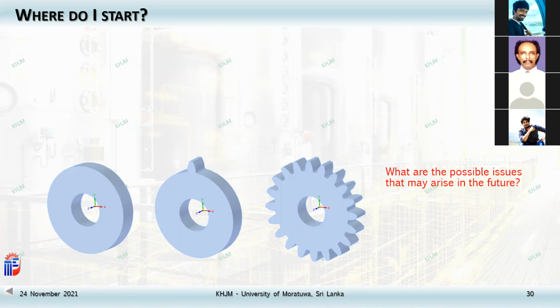You know the motor speed, you know the output speed, the required speed. So you divide, then you can get some values. But based on that, then you calculate the number of gear teeth. The number of gear teeth cannot be like say 24.5, 24.6 or something like this. It has to be an integer, both the pinion and the wheel. So the final gear ratio, you need to calculate from the number of teeth.